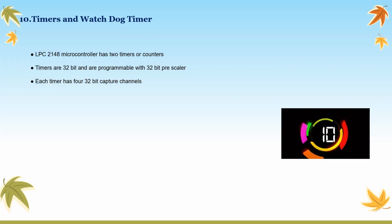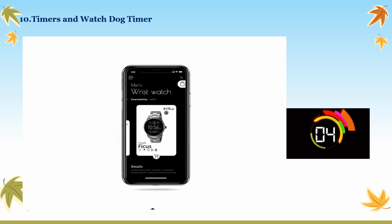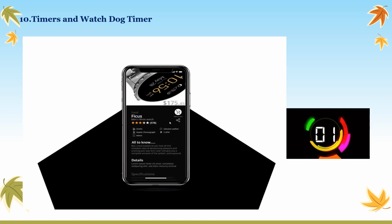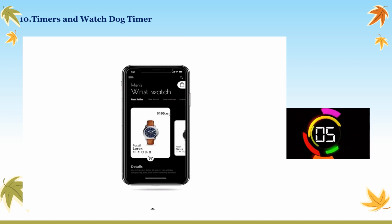This LPC 2148 microcontroller also contains the watchdog timer, whose main purpose is to reset the microcontroller within a specific amount of time during an erroneous state. After this, it again turns on the microcontroller within a specific time limit. Let us discuss some applications of the watchdog timer.